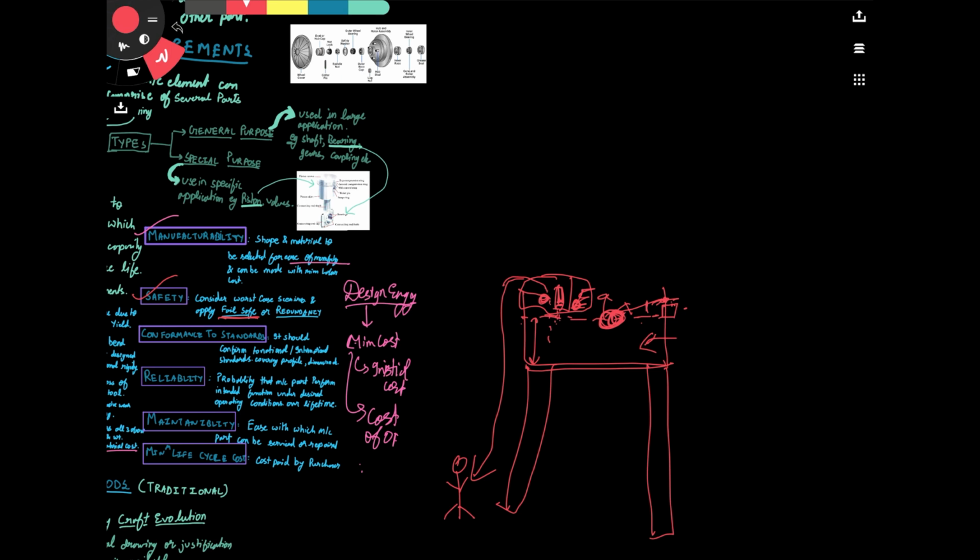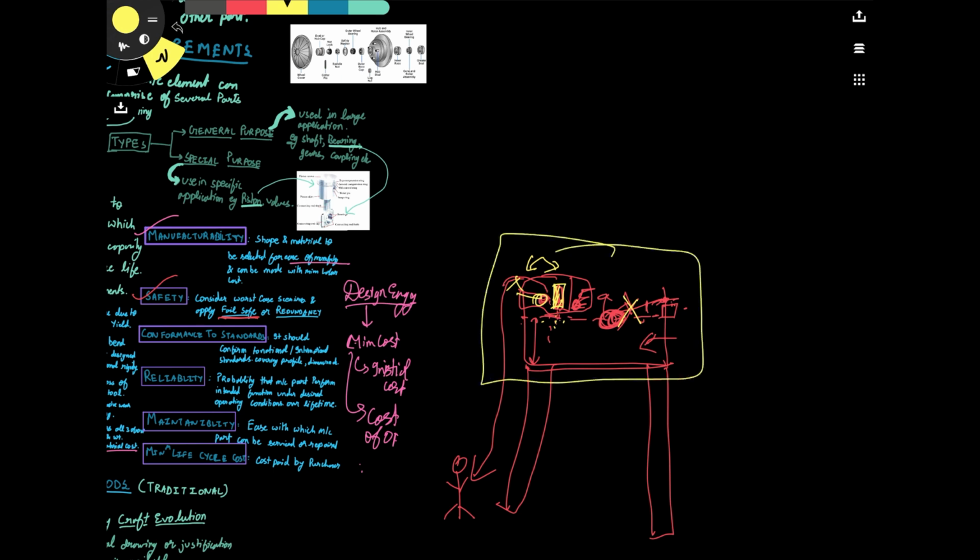Now, even if this particular float breaks, there is another float. Let's say this float also breaks, then this level switch, this ultrasonic switch, will give the command that the tub level is rising and it will stop the flow. So we have two different mechanisms here. The whole arrangement is known as fail-safe.